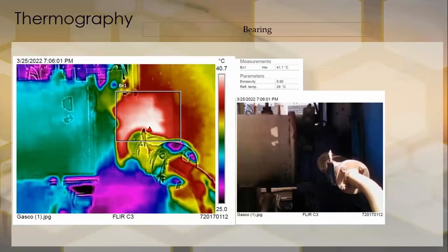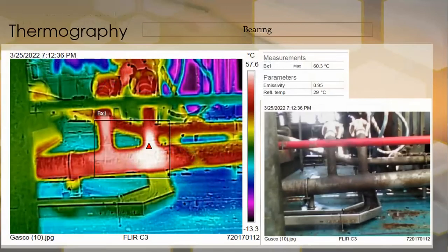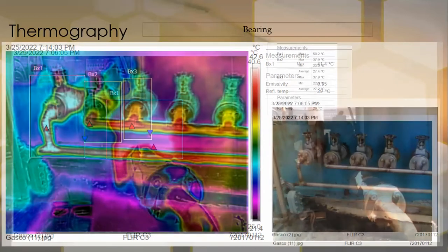We take our thermograms with a FLIR C3 camera. I'm so sorry for the quality of the thermograms, but this camera is without an autofocus or even a manual focus. It's just one focus, one condition. So it's all about the position and the angle. So the thermograms are a little bit blurred, but we didn't have any concern regarding the temperatures, so it was just an indicative way to see if there is a real problem or not. And fortunately, there was no real problem for the temperatures.